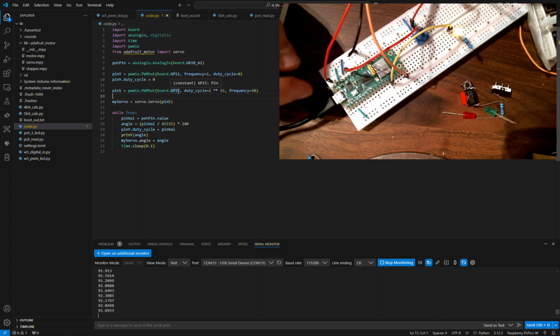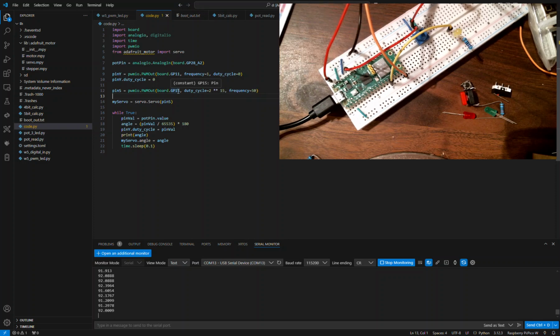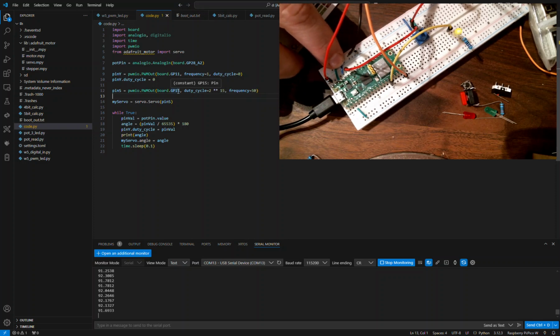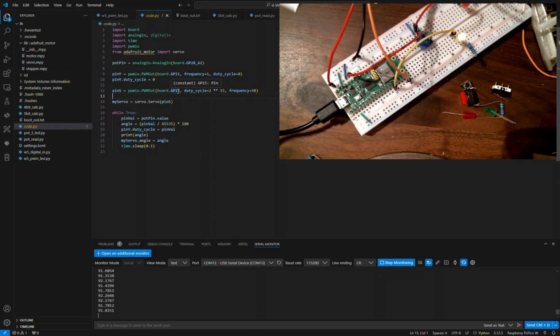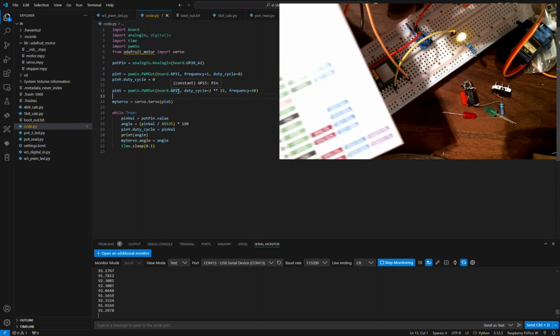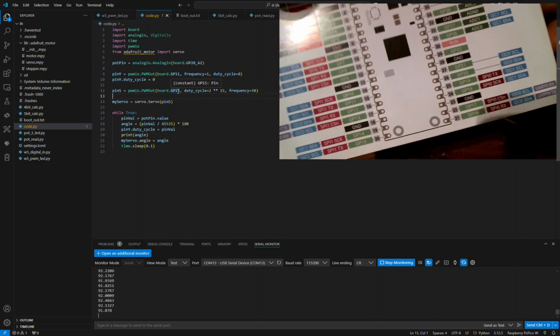For the red one, that's going to be your power. And so the red line we have hooked into not our normal power line. Normally the power that we grab is the 5th pin down, and that's the 3.3 volt power. But we need 5 volts for this motor, or for this servo. And so we're going to use, where do you go?